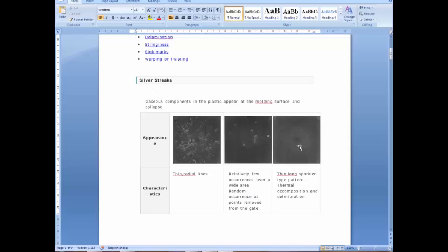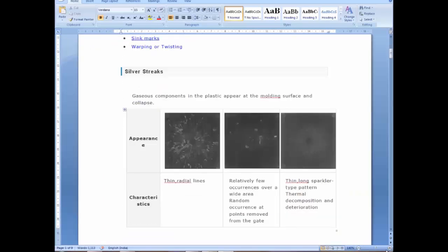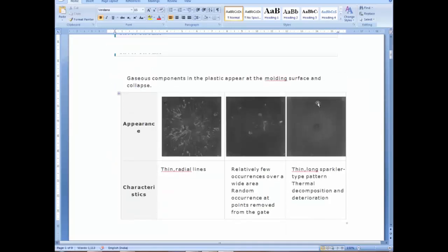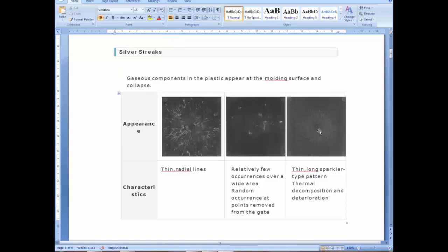An impression is created because of the gaseous reaction, and you can see these are the defects. Here are some fine lines. Here you can see some small white portions. These are there because gas was left inside the mold, and because of that these lines and defects are appearing.